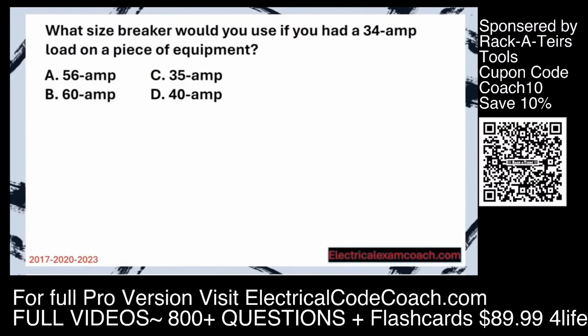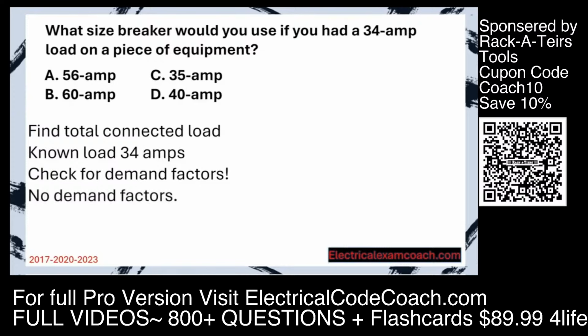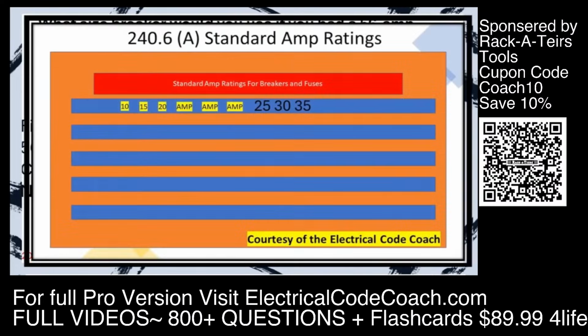Great job. What size breaker would you use if you had a 34 amp load on a piece of equipment? Step 1, find the total connected load. The known load as of right now is 34 amps, but we have to check for demand factors. There are no continuous loads, and there are also no specific pieces of equipment, so therefore there are no demand factors. We're going to head to our table 240.6(A), and we're going to choose the next size up, which in this case would be a 35 amp breaker.